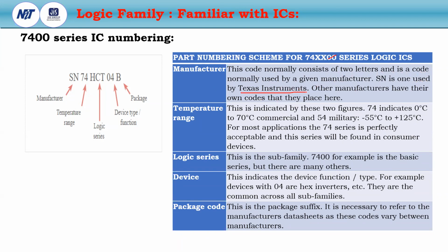This is an example. The first 2 or 3 letters signify the manufacturer's name. Here this SN is Texas Instruments. Other manufacturers set their own code. Now this is the temperature range, indicated by these 2 figures.